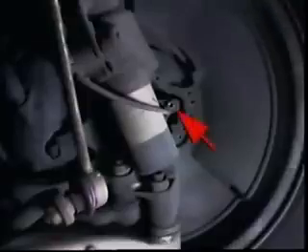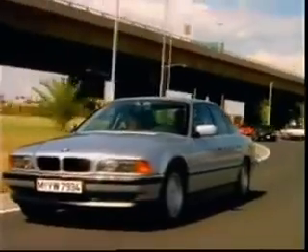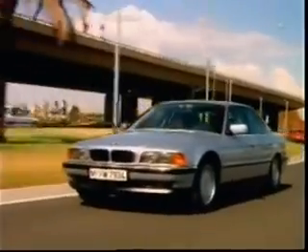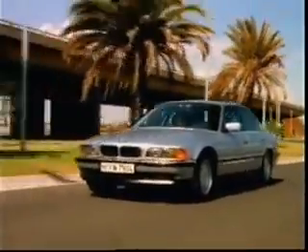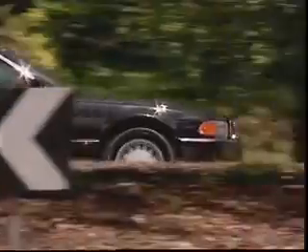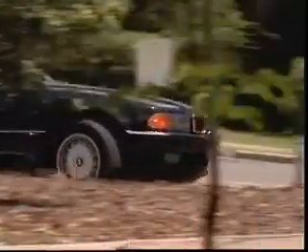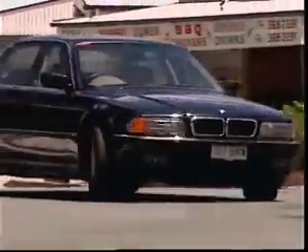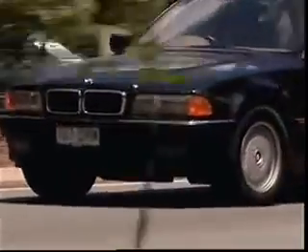For data from the wheel sensors to be accurate, it is essential the two front wheels have the same dynamic circumference. This is monitored continuously by the diagnostic circuits. Any discrepancies, perhaps from different tire pressures, will deactivate the corner identification.